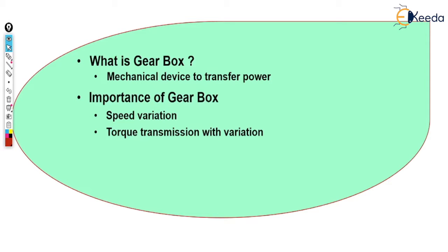In second gear the speed is more than the first, but the torque is reduced. At the highest gear you get the least torque. That is why, whenever we require higher speed, we use a higher gear, and whenever we require lower speed and more torque, we use a lower gear. Similarly, we have reverse gears also.